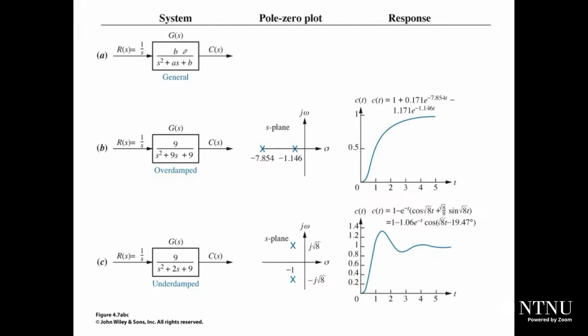So this is a transfer function of the second order system. This is the general form, SP divided by S squared plus AS plus P. This is the overdamped system. When you look into this response, it looks like, in fact, a first order system, right? Except that part, because this red one is, in fact, a response of the first order system. But because of that section here, you can discover that this one is a response of an overdamped second order system,